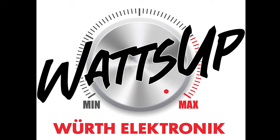Using suitable winding methods and the new series, such as Würth Elektronik WE-HCI and the WE-PDF flat wire inductors, this ideal case is very close to what we hope to achieve. The datasheet definition must also be looked at here. We need to ask ourselves, is the DC resistance specified as a typical value or as the maximum value required for calculating the circuit under worst case conditions?